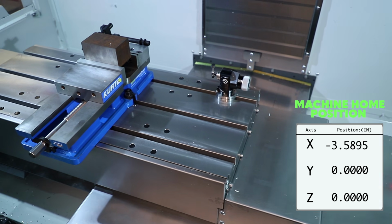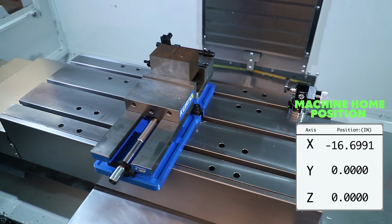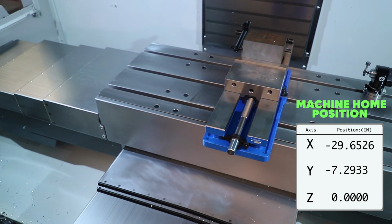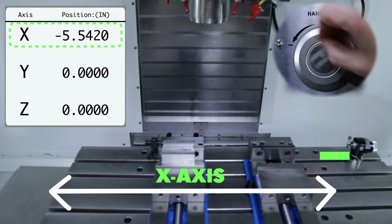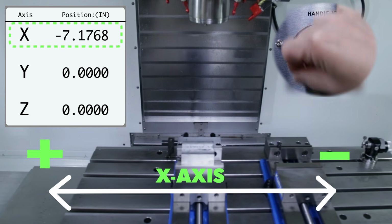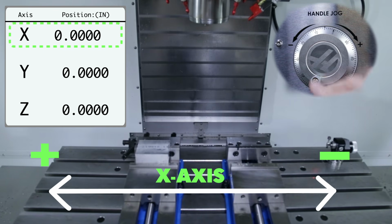As the table moves away from this position, you can see that the X-axis position readout is getting more and more negative. We say that we're moving in a negative direction. If we stop here in the middle of travel and start going back the other way, we can see that the position readout is now getting less negative. Now we're moving in a positive direction.